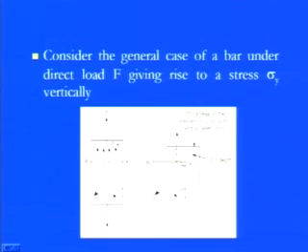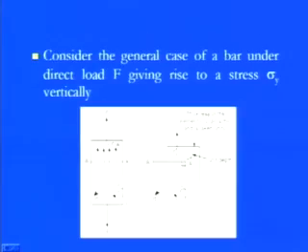If you are focusing on the main plane, then we have sigma y, but if we are considering the oblique plane, then we have sigma theta and tau theta, and if we resolve these stresses, we have the angle theta over this particular part. Now we just want to set up the relationship between sigma theta and tau theta, that means the stress components at the oblique plane, and the stress components at the outer surfaces, that means sigma y.